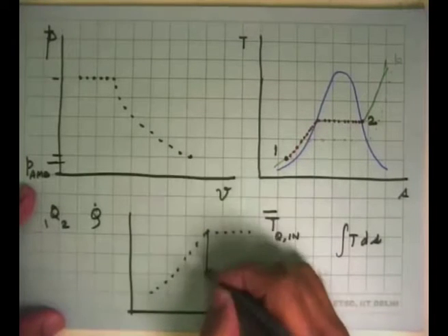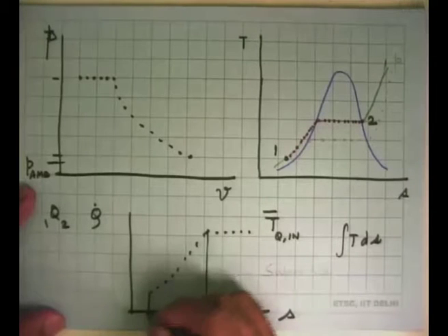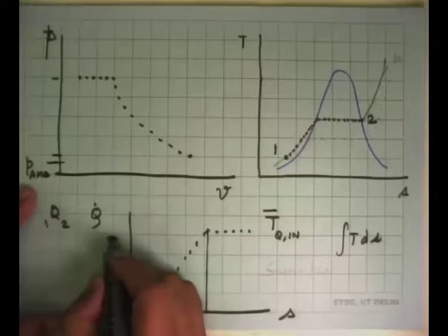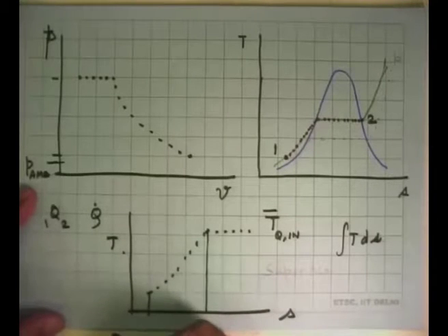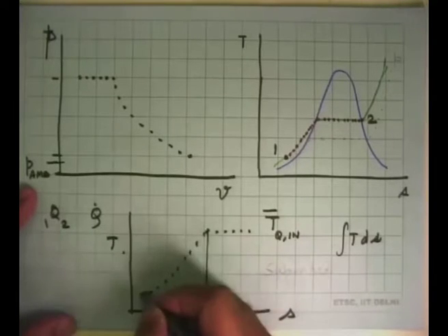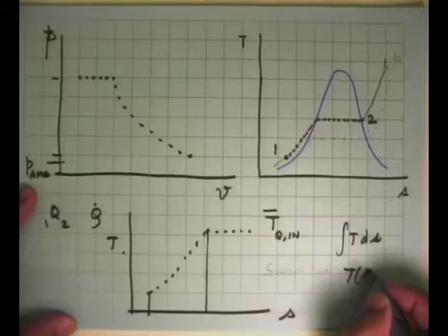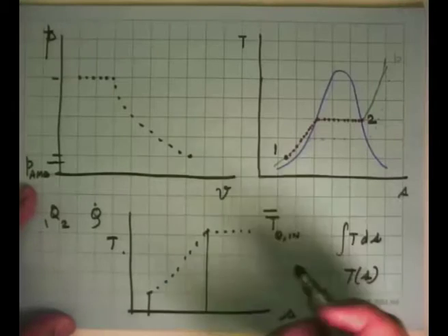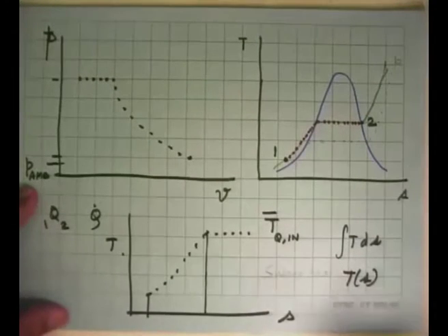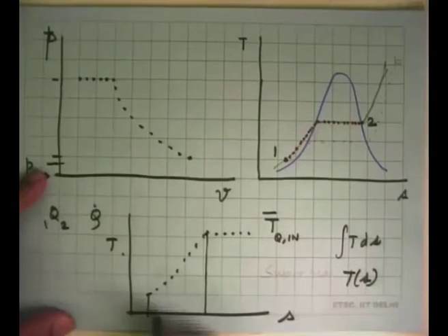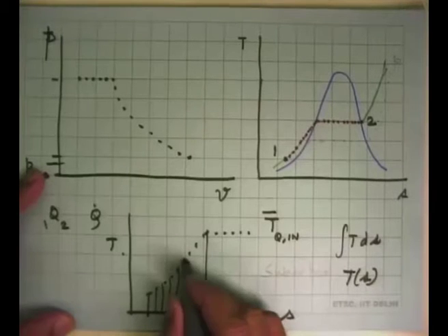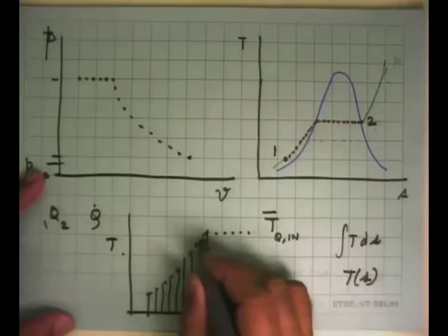But now what is happening is, we have a process where entropy is increasing and temperature is also increasing. So if we know explicitly T as a function of S, we can integrate this. The next best option, which is what we do now with computers, is to do a numerical integration and say, well, look, I will divide it into very small steps where there are small changes of entropy.